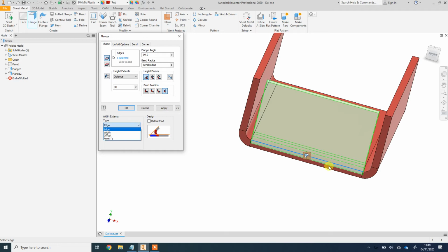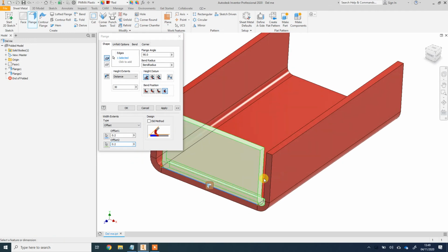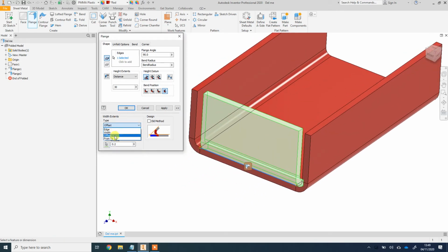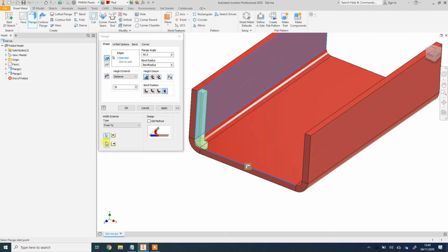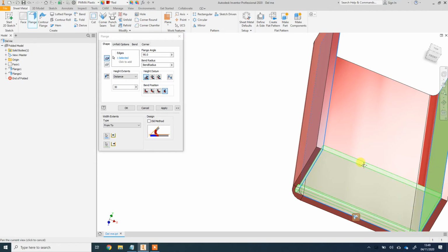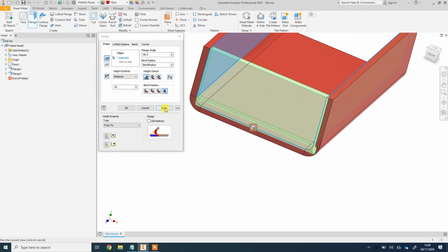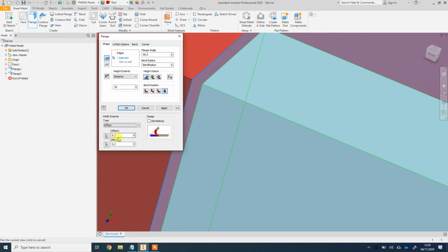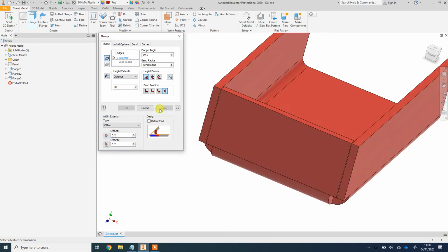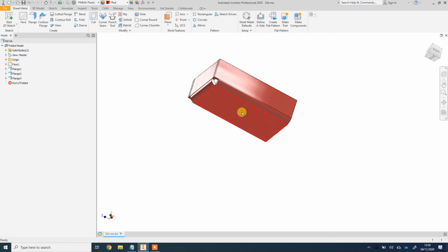What you can choose, and I've not quite figured this out, is you can choose offset. So if you type offset, look, type, I don't know, 0.2 and 0.2. Now that's not quite done what I wanted, sorry, I remembered now. So go from and to and pick one face and pick another face, but don't click apply. Then go back to offset, and there we go. Leave it at 0.2, and can you see that's put, look, if I change it, 0.5, 0.2, that's put a little gap between them. Click apply, and you can see what that has achieved there, another folded corner.